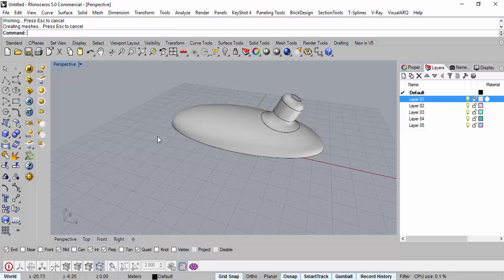In one case you will use the ellipsoid as a cutting edge and cut away the cylinder. In the other process you use the cylinder as a cutting edge and cut away the ellipsoid. Once you have that, you have to keep a space between the ellipsoid and the cylinder. So you'll have to cut away a little bit more portion, and then you'll have to use offset curve on surface so that you get some gap there, and then connect the two using blend surface. That's about it.